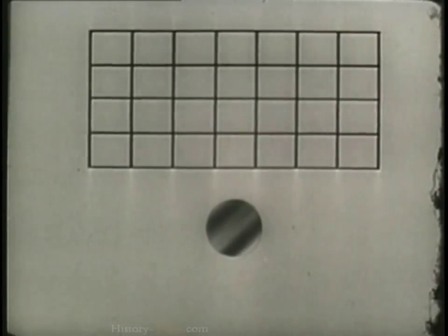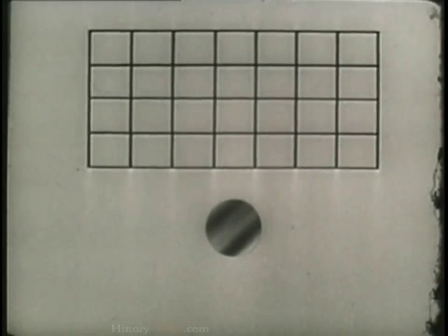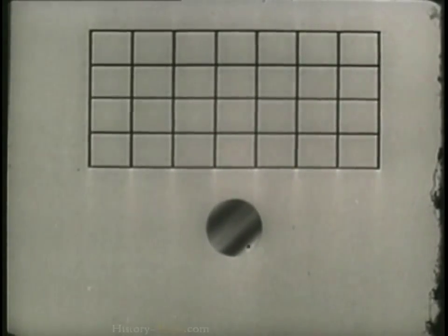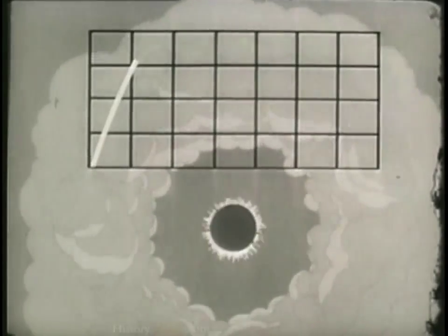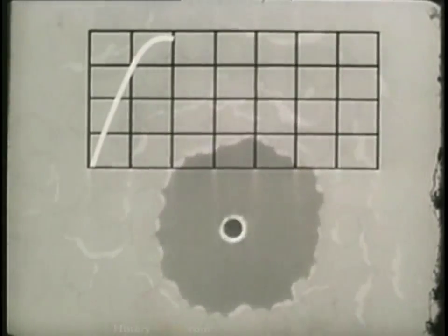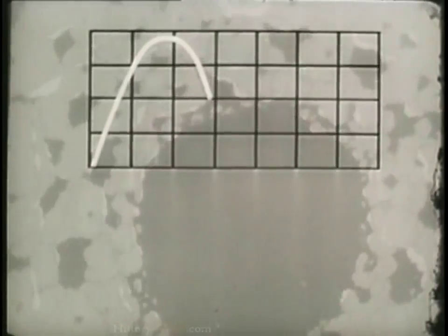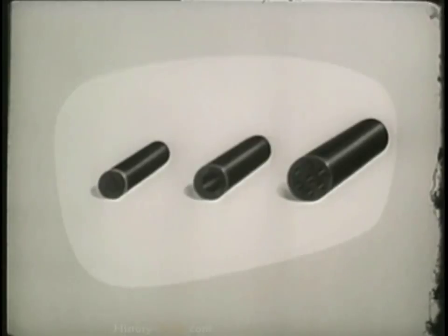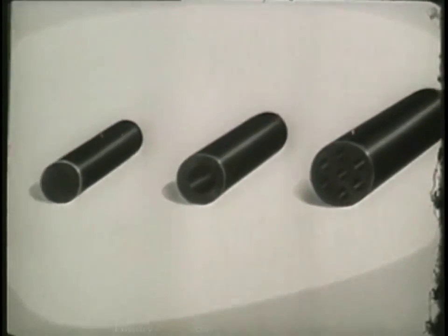As the burning surface decreases, pressure is generated at a slower rate. Here's a graph to show pressure action during burning. The degressive grain produces a very high pressure quickly, but the movement of the projectile tends to let the pressure drop off rapidly. The medium-sized grain with a single hole is called a neutral grain.